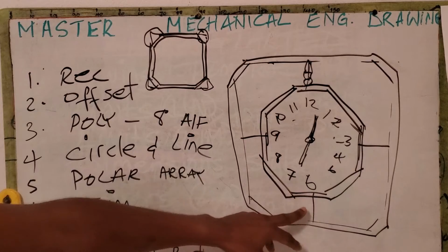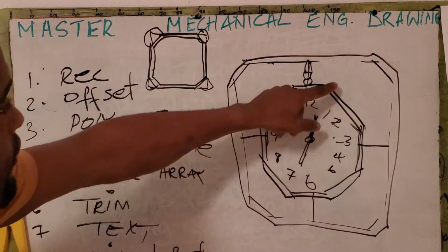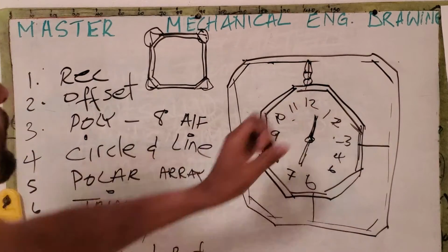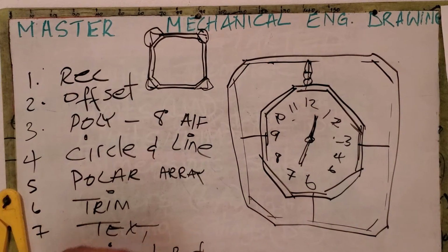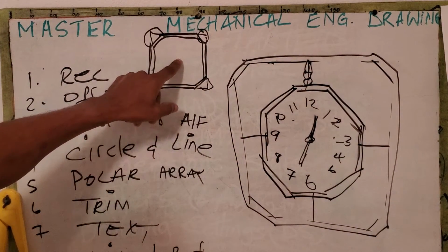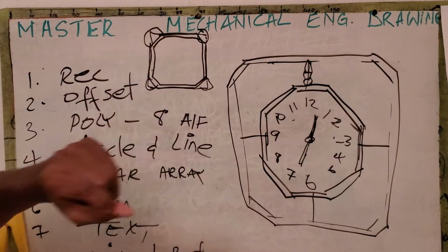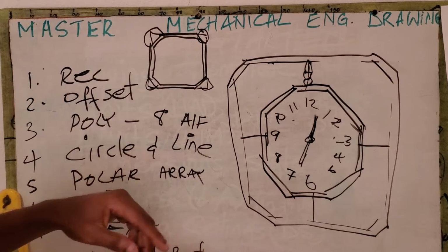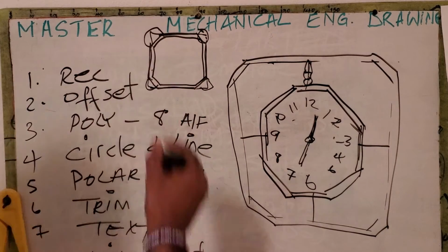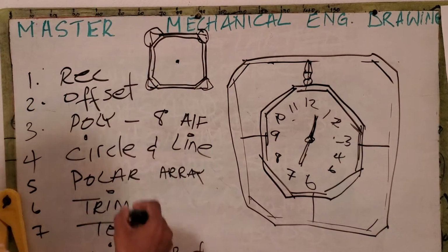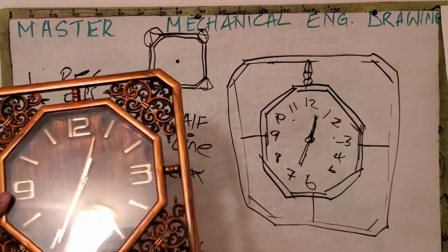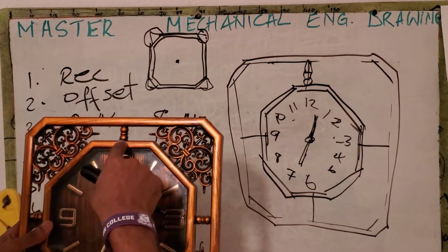My next step would be to draw a circle first. So I would click circle, establish my center by using either M2P or object snap tracking to get the center. Then I would drag from here to get this point here.